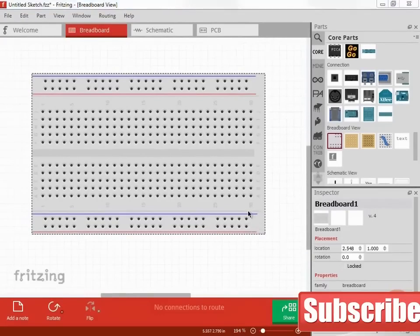The breadboard is separated down the middle with a channel. This is typically where an integrated circuit would straddle, so that all its pins land on isolated columns of contacts. The highlighted pins show areas of common electrical connection. The contacts are arranged in rows and columns.